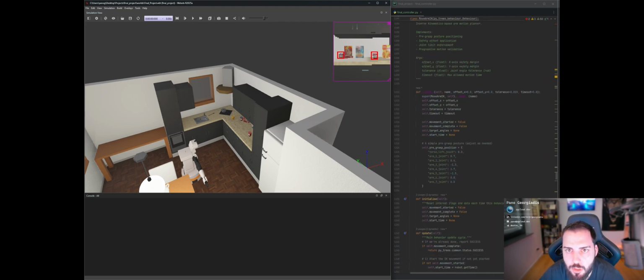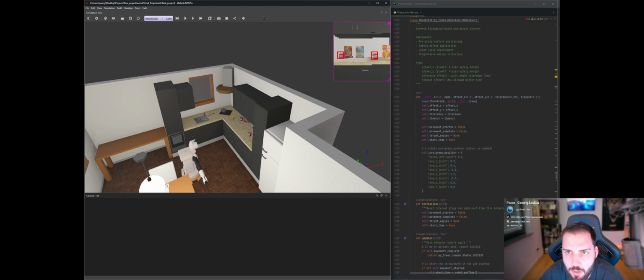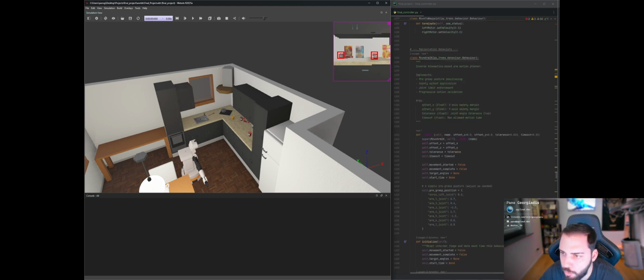Manipulation behaviors, the inverse kinematics based arm motion planner. This is one of the most important aspects of autonomous grasping in the controller file. It's a manipulation system that combines inverse kinematics and force-based grasping. The arm control implementation uses inverse kinematic solution with approach vector offsets for reliable positioning.